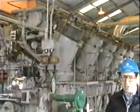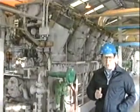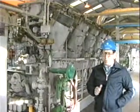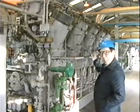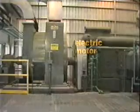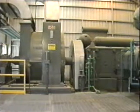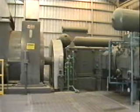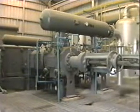Now let's take a look at the prime mover. In today's oil and gas operations, there are two kinds of prime movers used with reciprocating compressors: internal combustion engines and electric motors. Electric motors, coupled to the compressor crankshaft, are being used more often these days to eliminate hazardous air emissions and to cut down on maintenance and fuel costs.